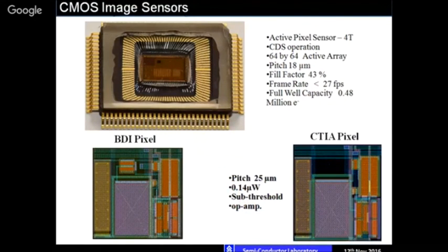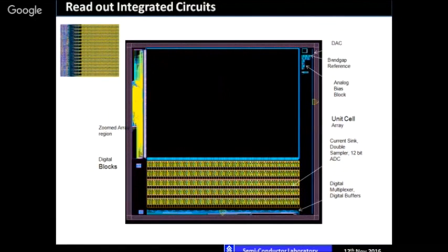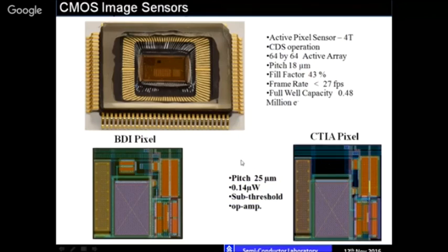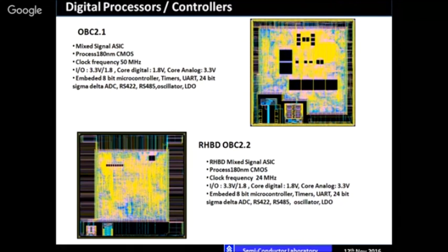This is in fact one circuit which is an APS, active pixel sensor, which is basically a CMOS camera. So this array, which is not shown here, has a photodiode here. It's a PN, and there are 320 ADCs which are placed here, the 12-bit ADCs, dual slope. Because this dimension is 320, it's an array of 256 cross 320. So 320 ADCs have been put here. So placement is very important in a circuit.